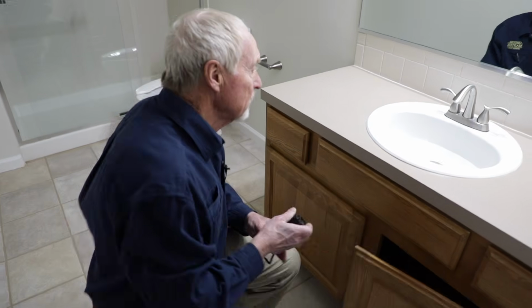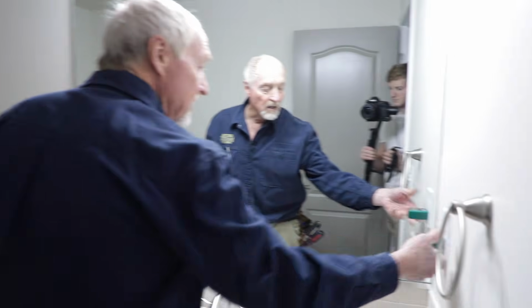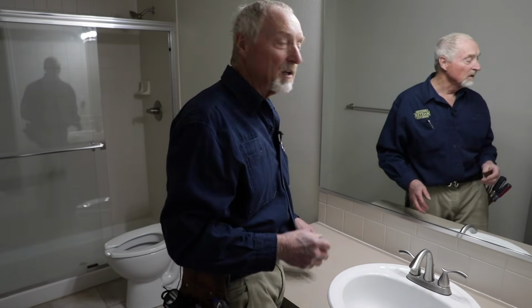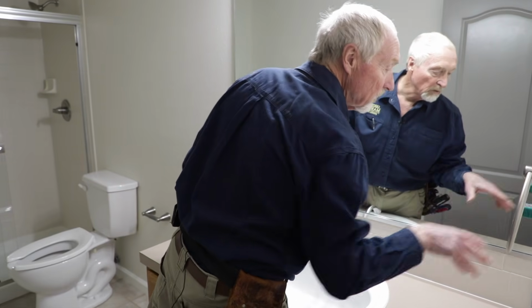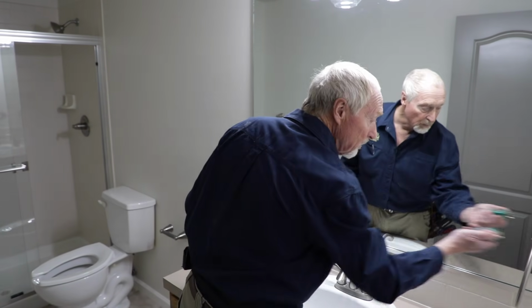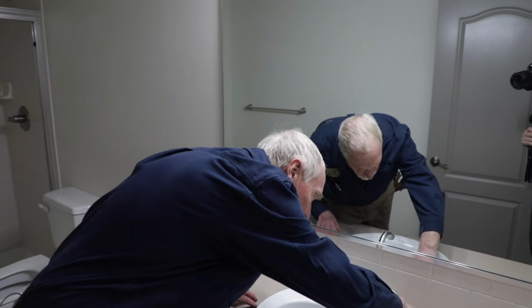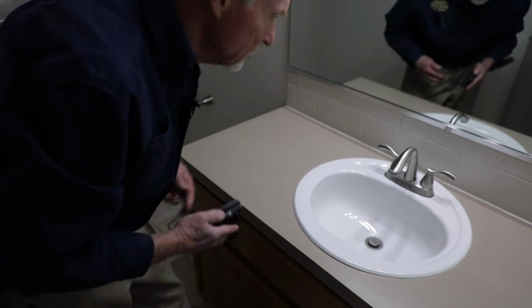And even though it's part of our electrical, we'll always check the outlet since I'm standing here and see if it's connected to a GFCI. And what do you know? We got the same problem we had up in the kitchen. Some polarity issue with the disconnect, and it's showing a hot neutral reverse after I hit the test button. So this would be a defect that we would include in our report, even though that's technically the electrical section. I'm looking along my countertop here. The caulking is a little loose there.